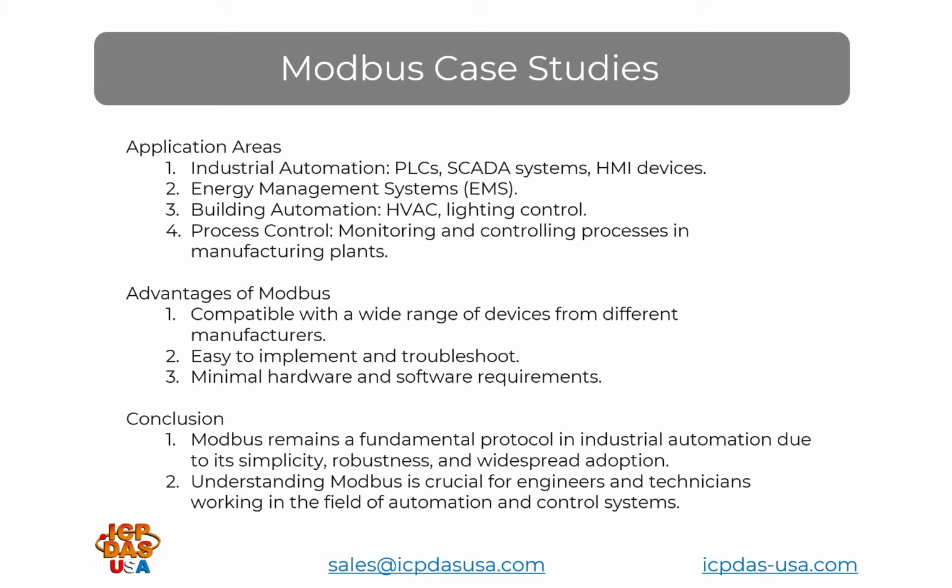Okay. What is the difference between Modbus RTU and Modbus ASCII? Okay, the difference between those are the physical command strings that you send. The commands and responses are going to be the ASCII equivalent of the Modbus RTU command. So for instance, if I think it was 32 was A, I'd have to look at a Modbus ASCII table.